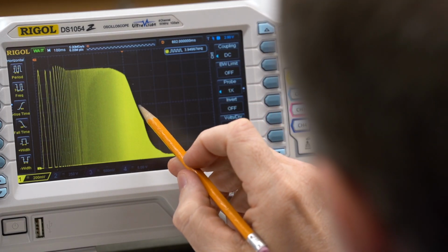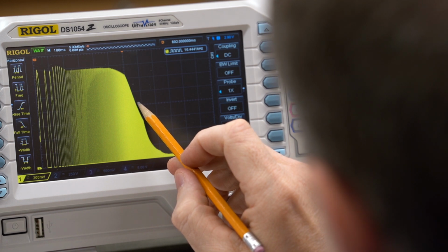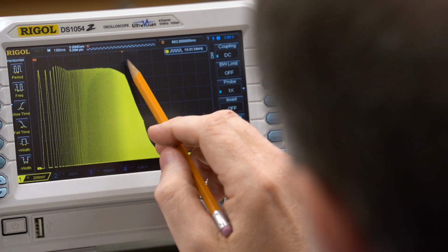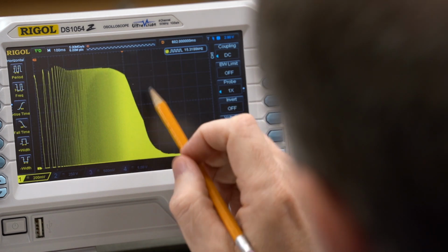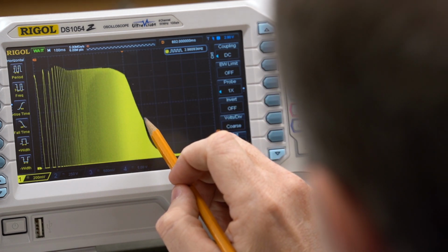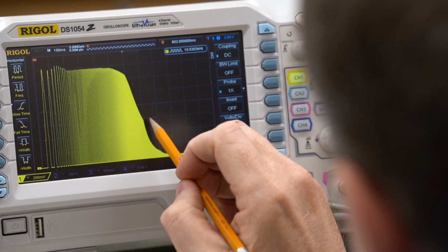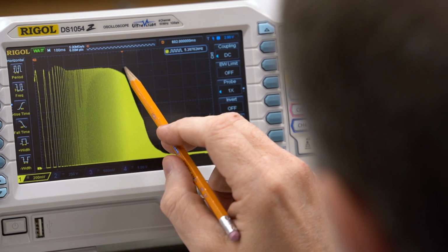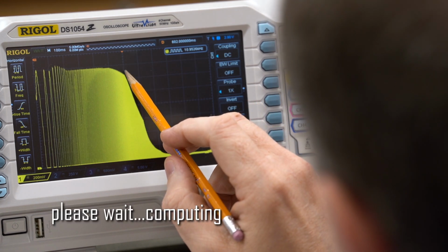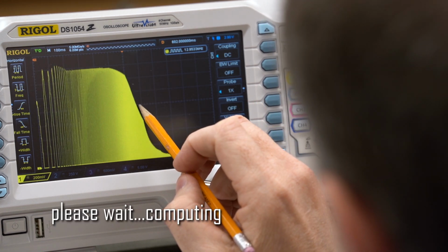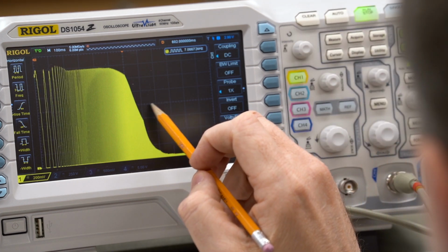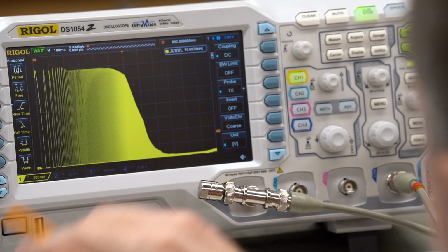Now the 50% point is now shifted a little bit to the left, and so we're at 10 hertz, 100 hertz, 1 kilohertz, 10 kilohertz, 100 kilohertz. So now we've lost about half of that. So this is a logarithmic scale, so we have dropped that down. Let's see, if this was 100, and now we're back past 10, so what is that? 30 kilohertz. We've taken it from 100 kilohertz down to 30 kilohertz.